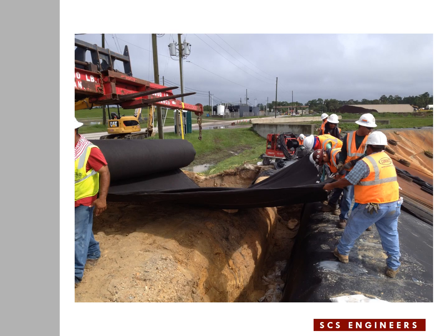After the geomembrane is complete, then they pull the geocomposite panels over the geomembrane. This is a double-sided geocomposite that gets pulled over the geomembrane. It gets anchored in the anchor trench at the top of the slope and extends all the way down to the bottom of the slope to tie into the lining system at the bottom of the disposal cell.